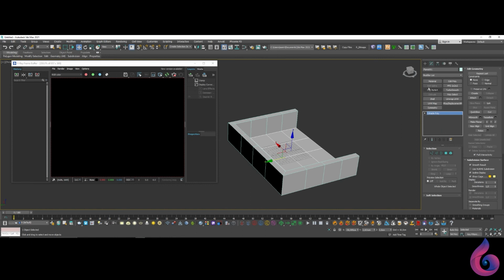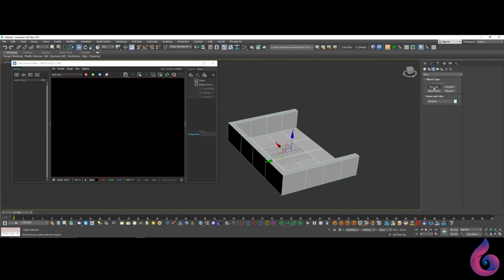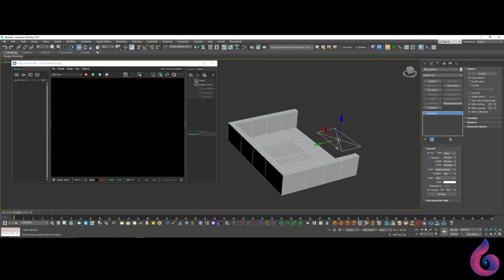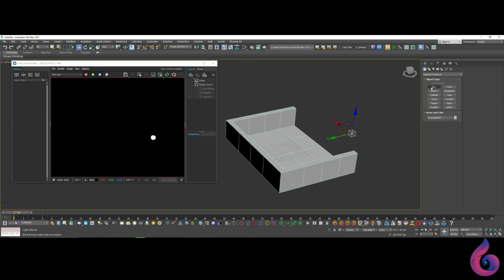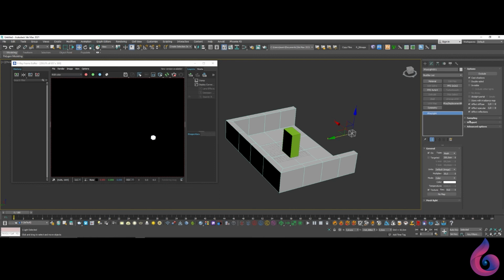Another way is through V-Ray Mesh Light. From the command panel select V-Ray Light, create a light source. From the modifier panel, under Type select Mesh. Create a box, press Free Mesh Lights. From Mesh Light pick the box and it becomes a light source.